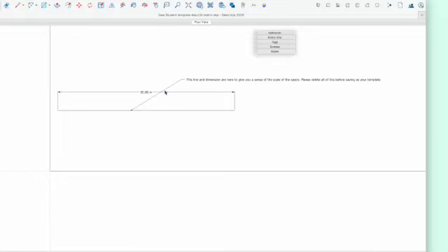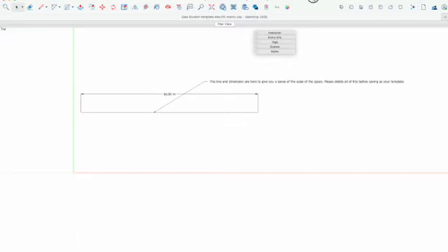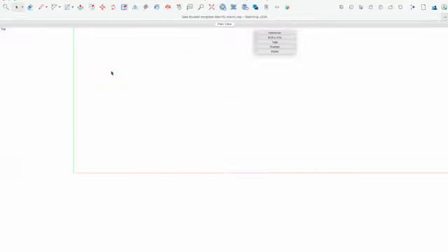Clicking on it will open the file, and this is what you see. That line with the dimension line over top is something I included to give you a sense of the space. Otherwise, it's really easy to draw a huge model and the program gets draggy. So you can use your mouse to click on those lines and press delete, or you can select the Eraser tool from the toolbar up top and click on the lines, or you can use a selection window, which means you click and hold then drag your cursor across the items you want to erase and press delete.